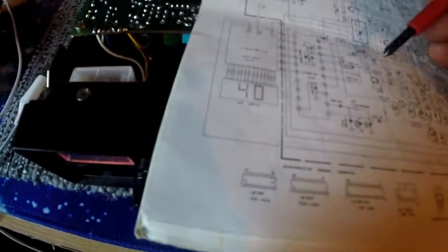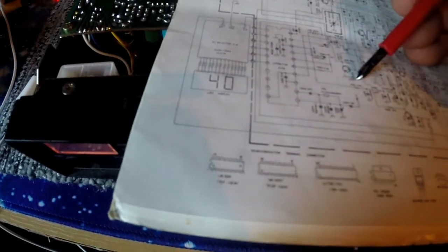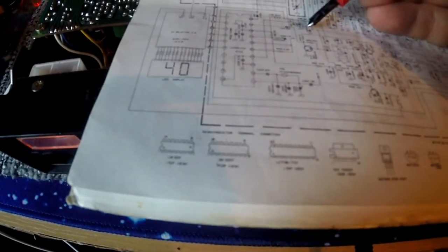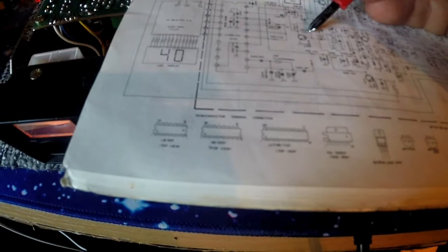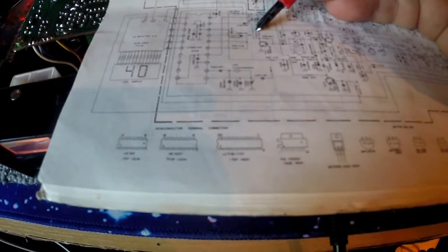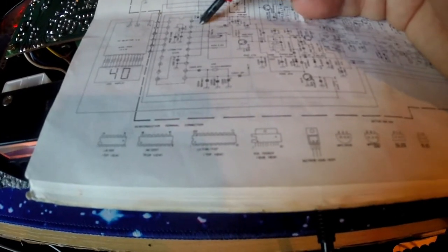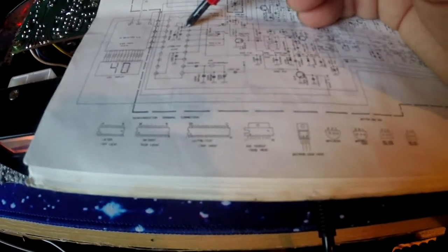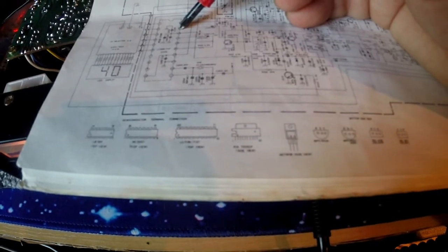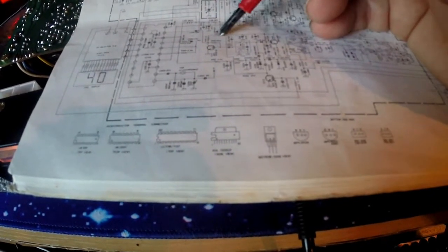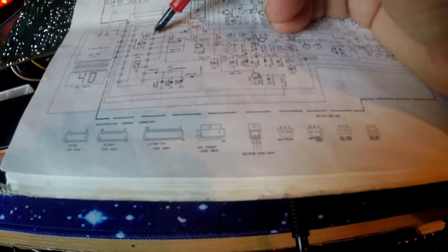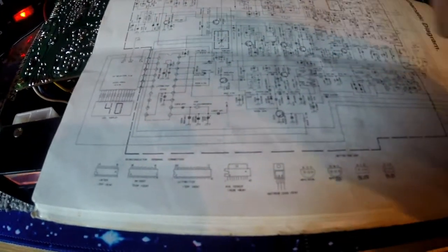Now, the components that I've got, looking at the circuit diagram, and I will zoom in to show you, are R156, Q113 and R155, and C198, all of which go to pin 19. So the frequency going in to the LC7137, the PLL chip, is being stopped in this area here. It's not making it to the pin, and that's why I've not got lock.